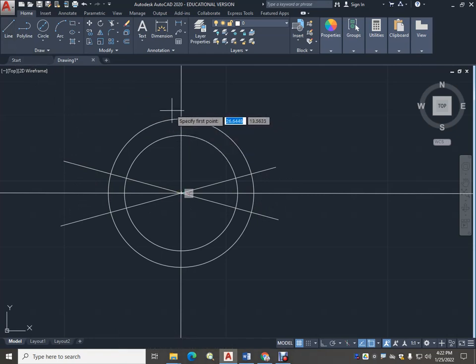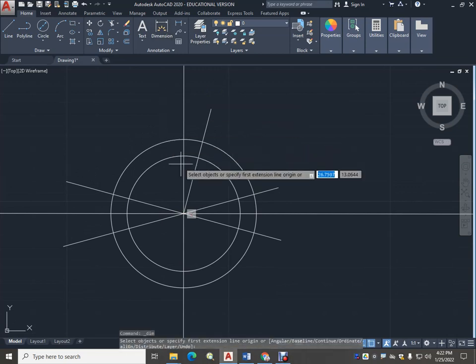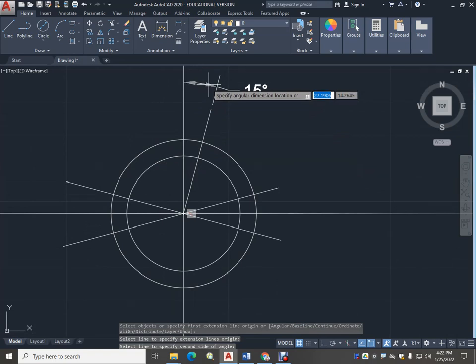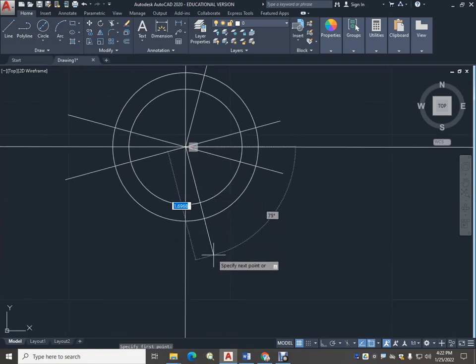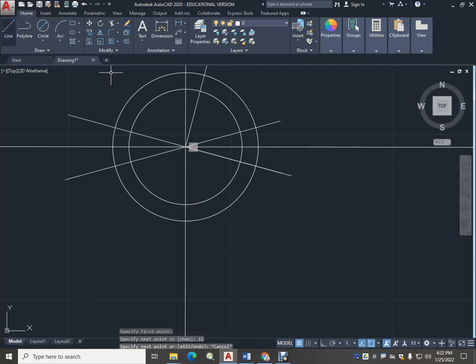Here we want one going across the vertical tail, and you'll notice that this is 90. So if I take that and minus 15, I bet you I'll get 75 degrees. So let's hit the tab key, put that 75 degree in. Now let's just check, and I bet you we can get 15. There it is. So there's our 15. Let's do it on the bottom side. Hit the tab key, 15. Oops, not 15, I'm sorry. 75.